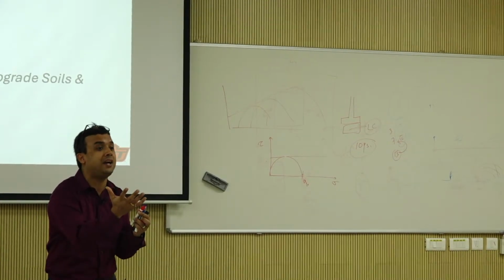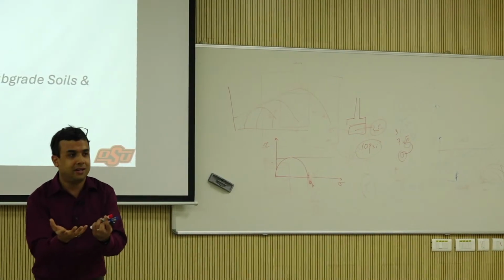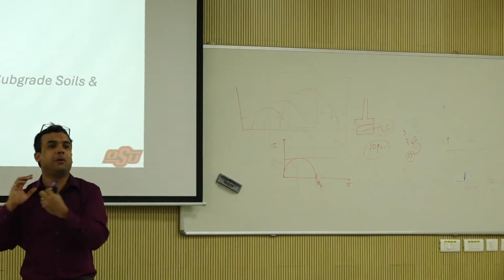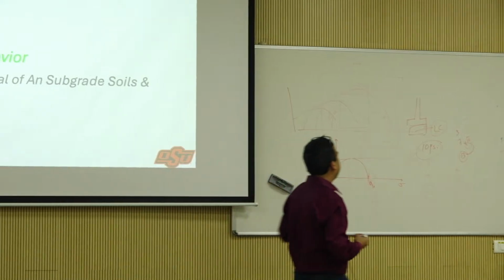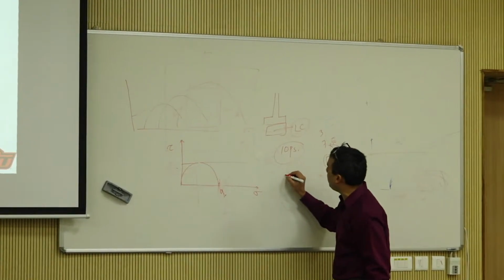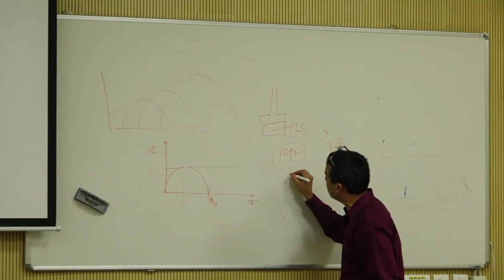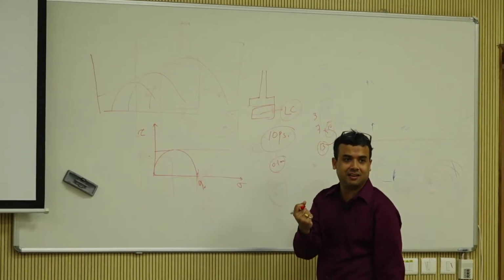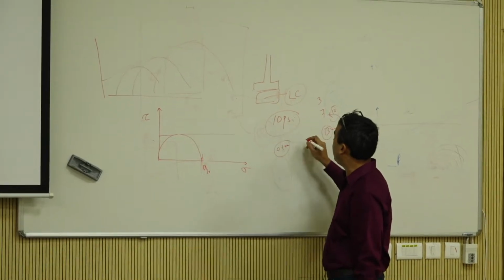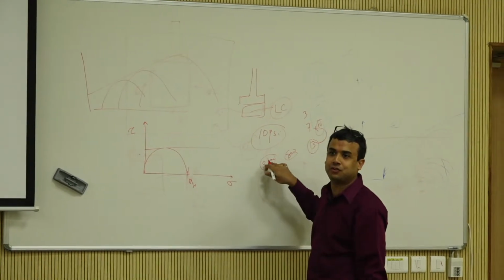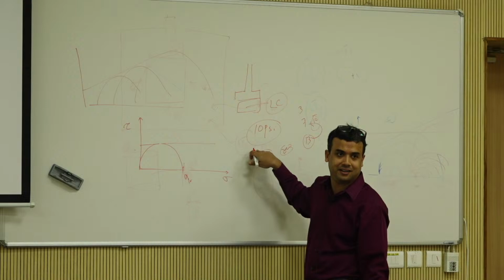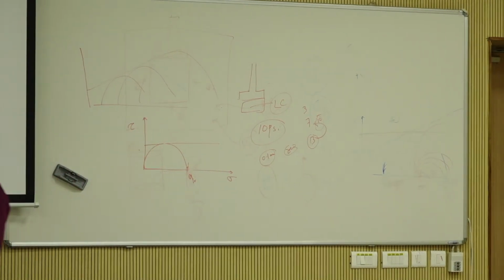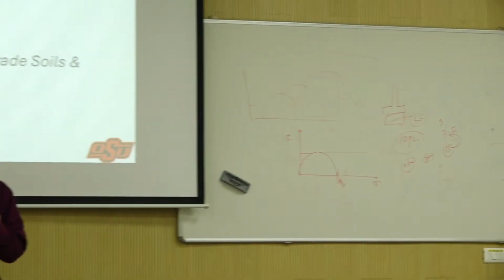What is the force dependent on? Your sample. I just showed you when he was trying to push my hand, I moved, so the thing was moving, right? So the machine actually is just saying, even if it is a stress control test, that I'm going to apply 0.1 millimeter of deformation, and let's see how much force I'm feeling. If it is not 100, if it is 2000, it's like, oh wow, this is way too much, I need to go 1/10 of that. So a machine doesn't know anything other than applying deformation, right?